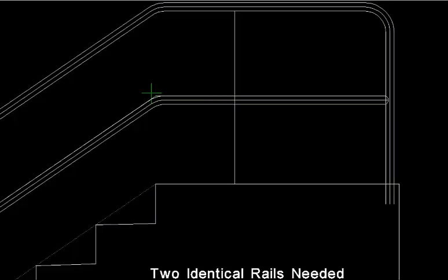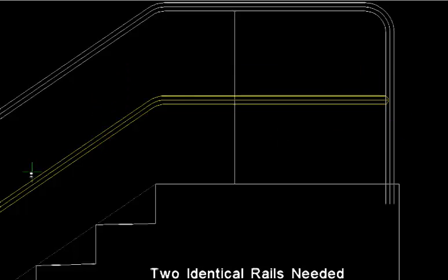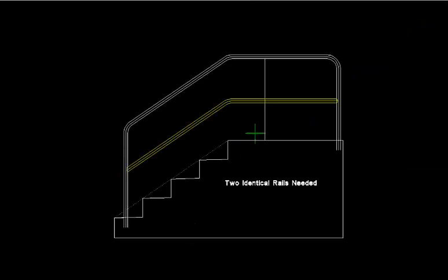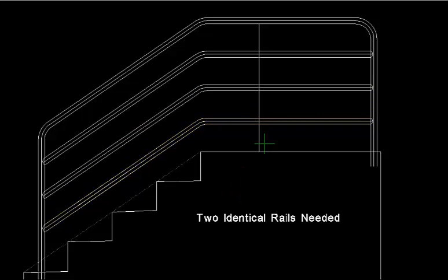Oh, let me stop here. I forgot to erase the geometric shapes. I want to copy all of them and erase them later. Measure this again. Pipes. Selecting what I want copied. And then when we press enter, copy the pipes and put them in place. That's a pretty good time saver.